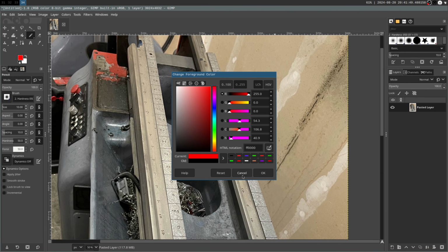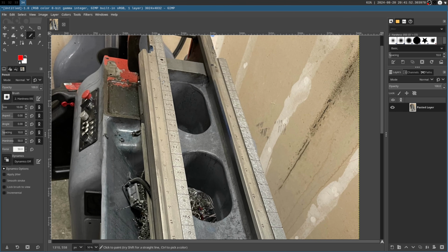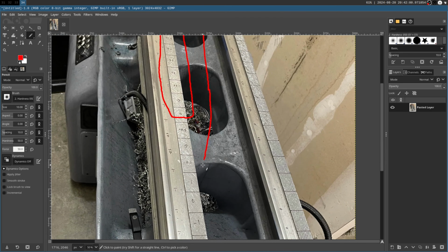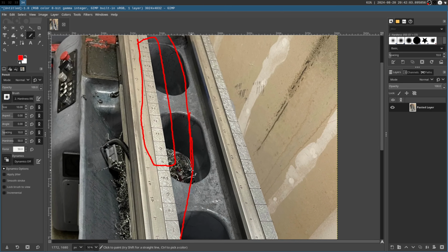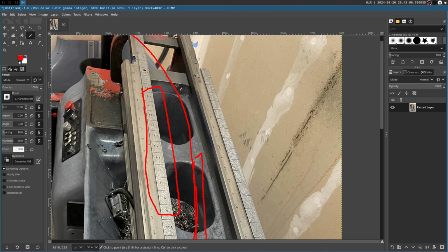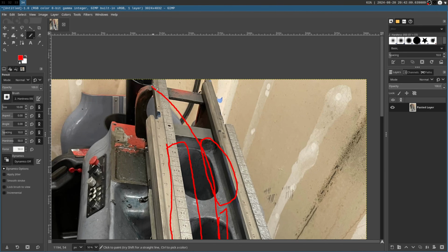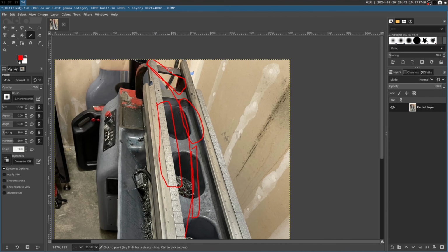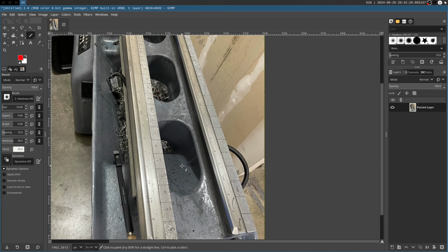Now, getting 2 surfaces in agreement with each other is hard when you have a straight edge that isn't as long as that surface. Because in theory, I can put a big bow on the surface, and that straight edge will sit relatively tangent across the entire thing as I move it, and I get an inaccurate reading where basically everything is being marked. But if I had one big straight edge, it would say that these corner parts are so low and there's no contact there, and the blue would only be in the center, right? And that's the hard part of doing this work.